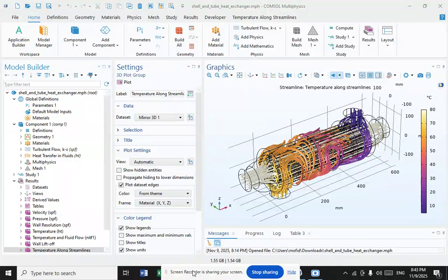And what about the fin tube? The usage of fins in a tube-based heat exchanger is common when one of the working fluids is a low-pressure gas and is typical for heat exchangers that operate using ambient air such as automotive radiators and HVAC air condensers. Fins dramatically increase the surface area with which heat can be exchanged, which improves the efficiency of conducting heat to fluid with very low thermal conductivity, such as air.